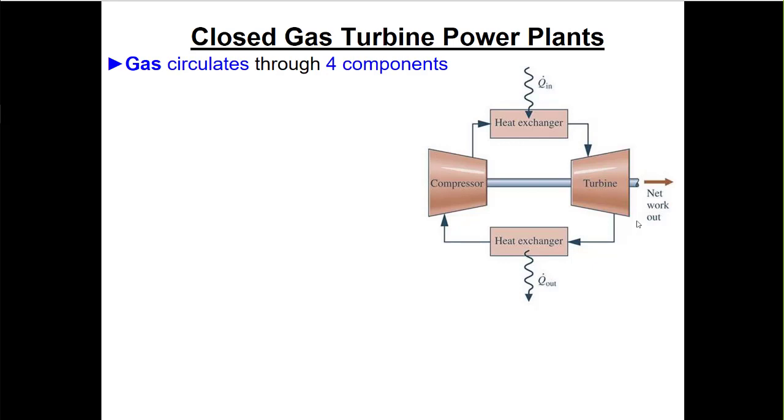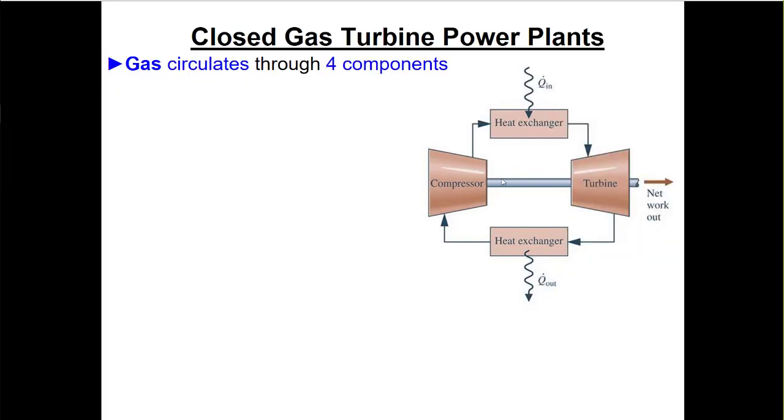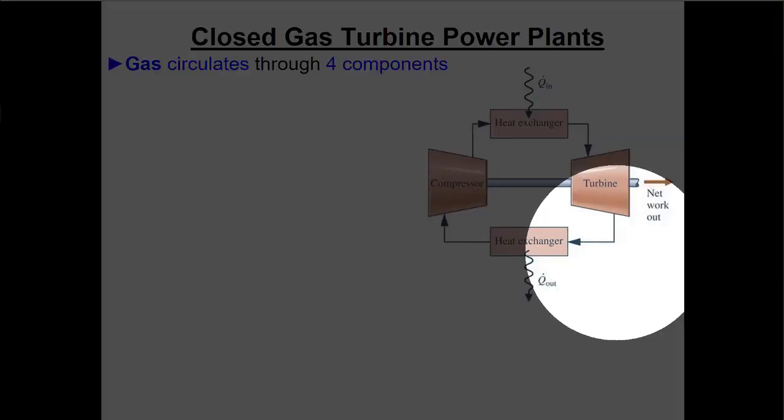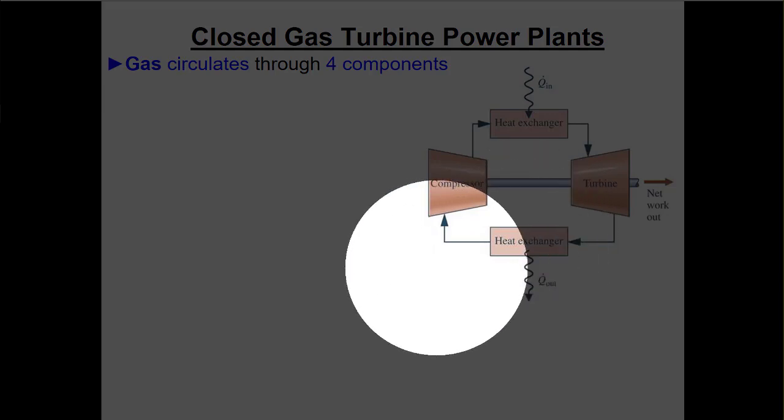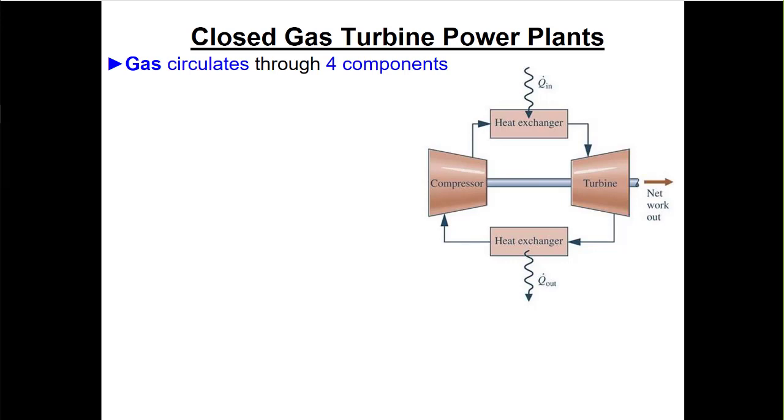Right? So if we think about this as a closed system instead of an open system, as a series of closed systems. Here, when we say closed, we don't mean closed in terms of the internal combustion engine. We mean that the whole system is a closed loop. So if you hear someone talking about an open Brayton cycle, what they mean is that this heat exchanger doesn't really exist, that you're pulling air in from the atmosphere and you're exhausting air out to the atmosphere.